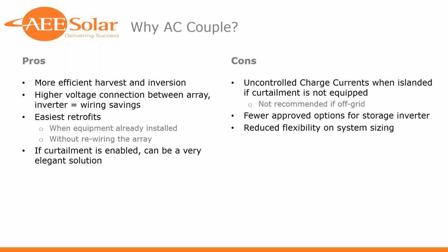Really what I see in talking to customers out there is, they might get called back to a system they installed in the past. Customer wants to know why, when the power goes out in the neighborhood or the transformer goes down, they don't have power, and you're looking at a retrofit. When the equipment's already installed, it's really tough to tell a customer, I've got to take some of that off, I've got to rewire, there's a whole lot more work involved, and I've got to add a battery inverter and a battery bank, etc.